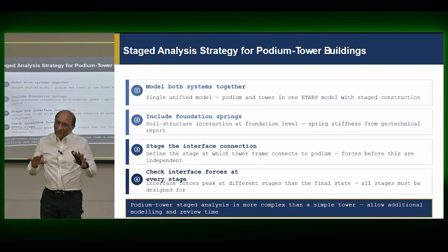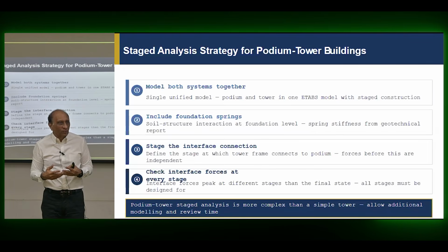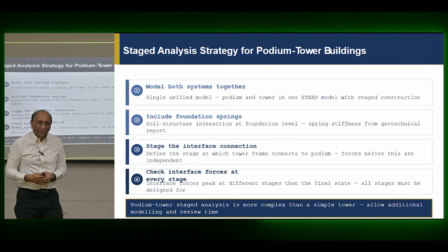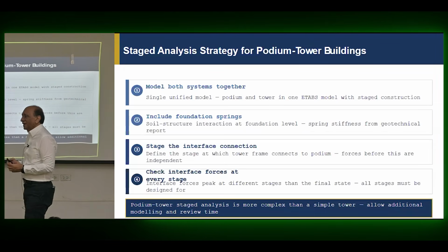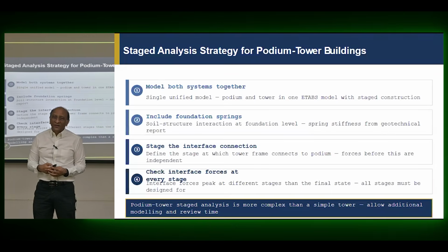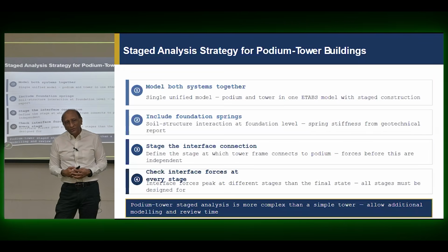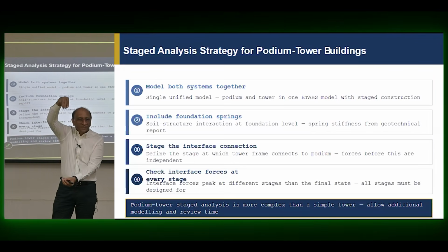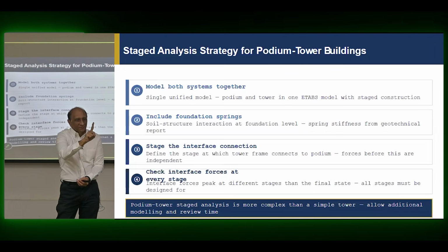Once you have a clear understanding, then you can go ahead and create a full model, just for fun, and you can see some results. But it will not give you understanding. If you just rush and create that model, you will spend 1 year creating a model that you are not sure is correct or not. So always do a simplified stick model. Some people will just do a stick. They will consider each tall building as one cantilever, because that's what it is, right?